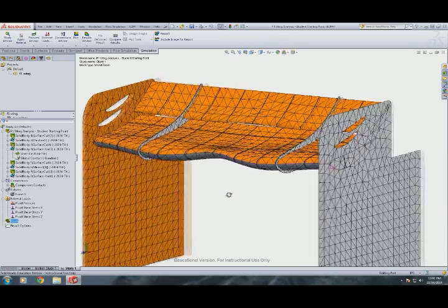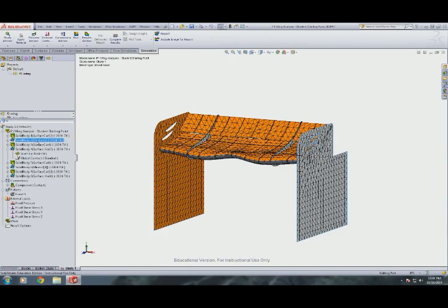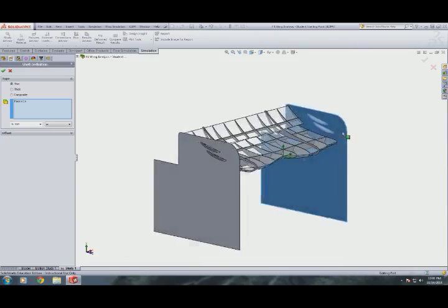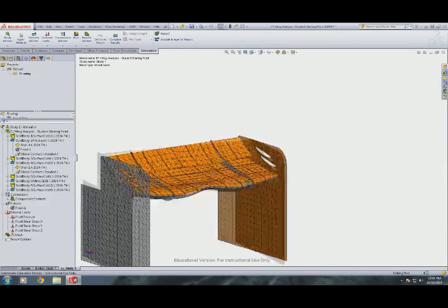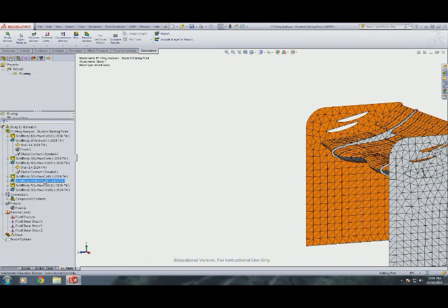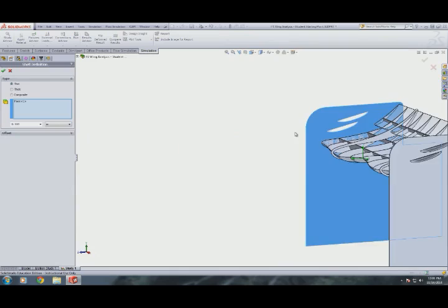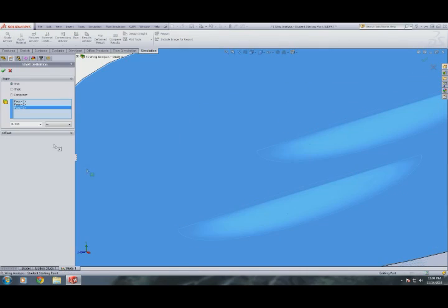So let's go check out the... Is that one of the shells we need? Yep. We have to expand it. Right-click shell 4 and say Edit. At that point, we have to add in these little vents, or else they're not going to exist in the finite element analysis simulation. I know that'd make everyone really sad. Right-click here, shell, edit definition. Again, just adding those in. Fix the mistake, fix the oversight.